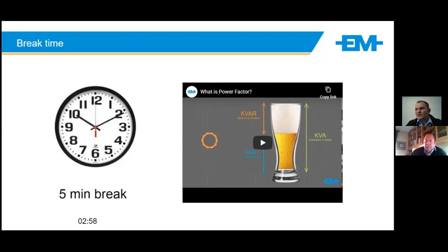Okay, so on the variable speed drive, again, it's down to the type of variable speed drive. So based on the discussion around the pulses, you would have a 6 pulse, 12 pulse, 18, 24. The more money you spend on that variable speed drive, the smoother that waveform is going to be ultimately to the motor and to the grid supplying it.